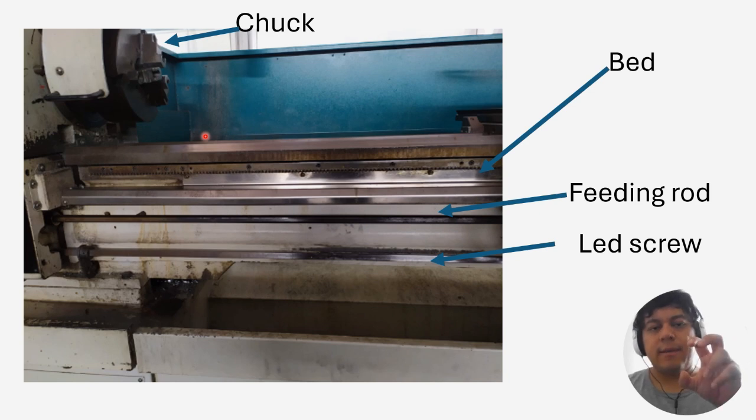So these little teeth, well, it's not that little, but these teeth, let's call them that, are going to compress in order to decrease its diameter and hold the piece very tight. So let's suppose I'm holding here the part that I'm going to use for manufacturing. The chuck is going to decrease and hold it very, very tight. Of course, we want it to hold very tight because the main functionality of the lathe machine is to start rotating the part at high RPMs.